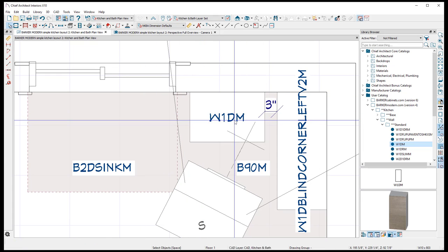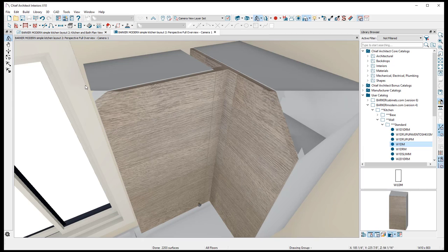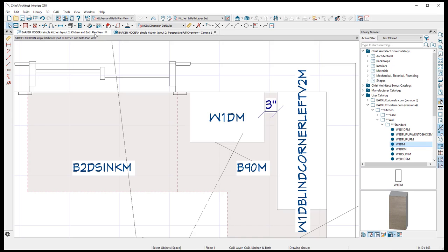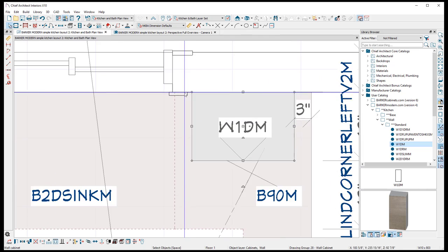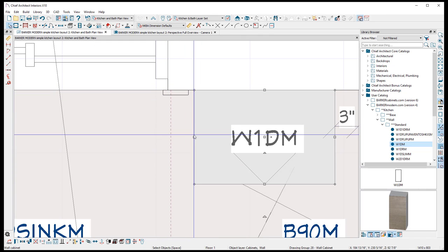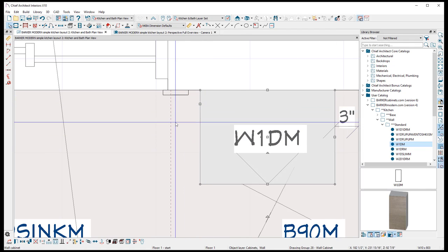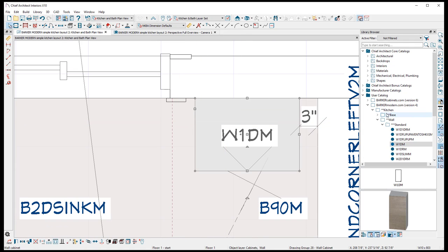It's not good. All right, so double click on your wall cabinet right here. Just make sure it's not into the casing. We're going to need a finished-in panel on the side here. Notice we don't want to have this showing when you're at your kitchen sink. So let's bring that back just a little bit. You can see the casing is outlined right there. Let's take that back just a little bit more. There we go. Perfect.